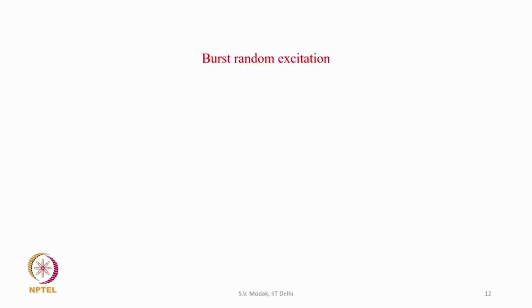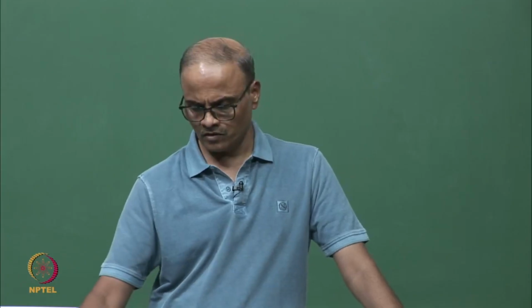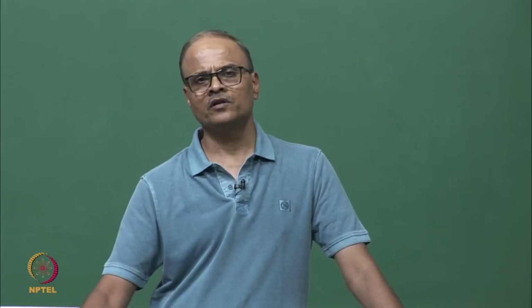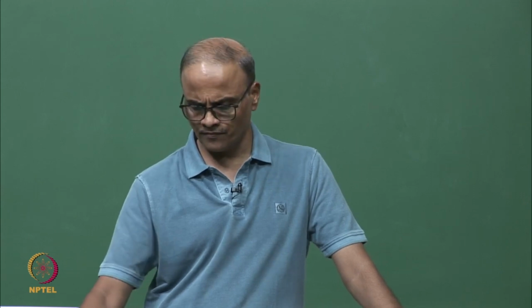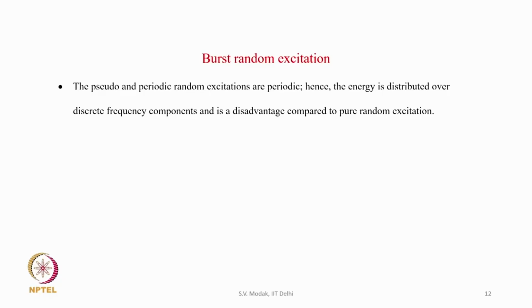Let us look at another variant of random excitation called burst random excitation. Is there any disadvantage associated with pseudo and periodic random excitation? The pseudo and periodic random excitations are periodic, hence the energy is distributed over discrete frequency components, which is a disadvantage compared to pure random excitation.